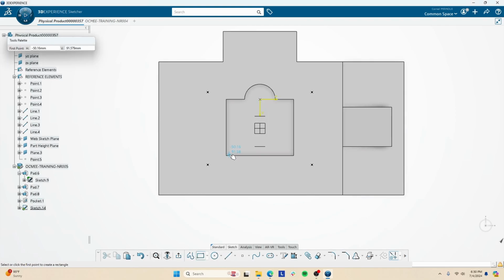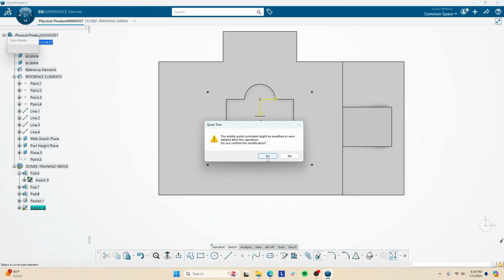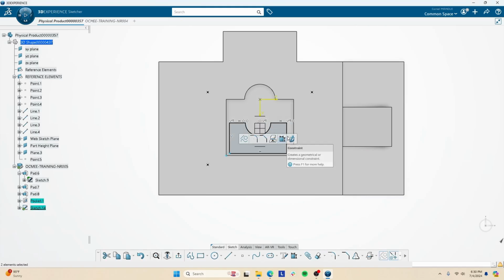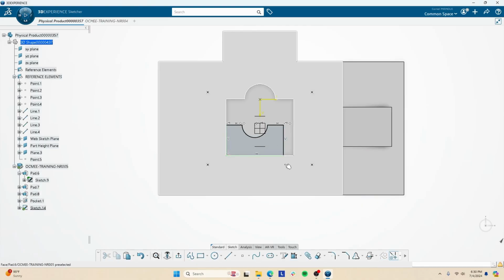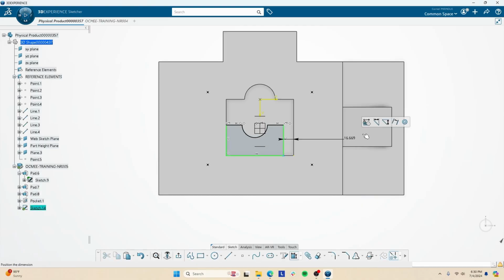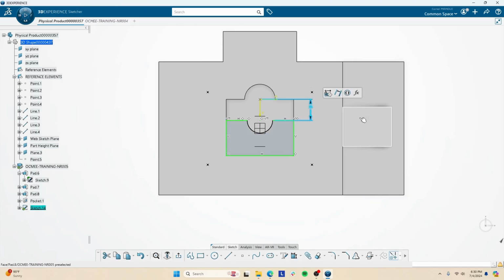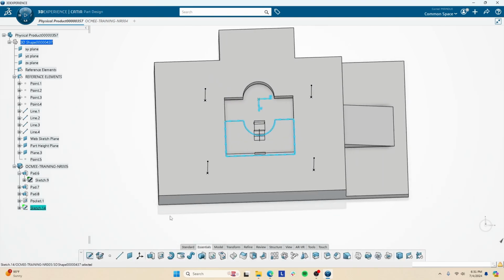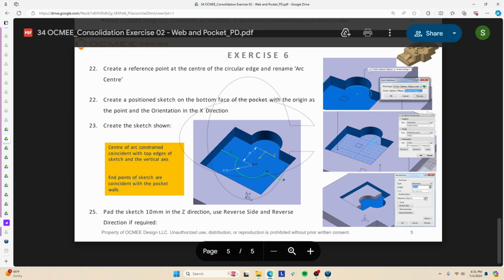So there's multiple ways I could do this, but I'll do it the more manual way. Make this point coincident to that point. Constraint, coincidence, same thing here. Constraint, coincidence. This was 35 away, with this being the same 25. Cool, everything is ISO constrained once again, and we could create a pad off of this. 10 millimeters.